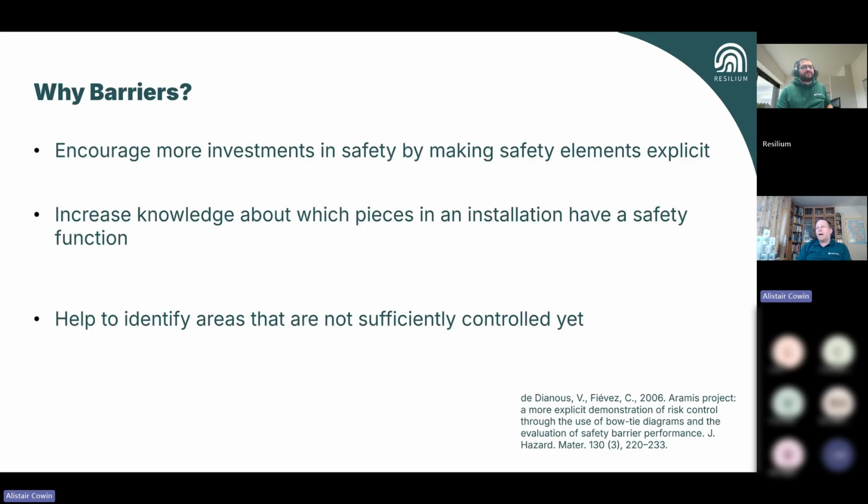Often people don't realize the impact that what they're doing has on safety, and it can be really inconsequential little things, sweeping up the floor. There was a massive fire at King's Cross in London that was essentially the build-up of waste products that caught fire in a spot that no one could see, that led to a huge fire. And it's as low down as the person sweeping the factory floor that can have an impact. When you lay things out in a bow tie and barrier thinking, you can see that quite easily. So it really helps people go, that's important.